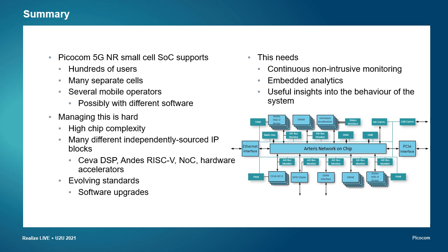Yes, thanks, Gad. That's a very good answer. One of the things I like about it is it applies to hardware as well as software. On an SoC like this, we have a lot of hardware accelerators, as we've seen from the diagrams. This is because although we'd ideally like to do everything in software, there's a balance to be struck between the silicon area and hence the price point we're designing to, the power dissipation that we have to meet, and the configurability.